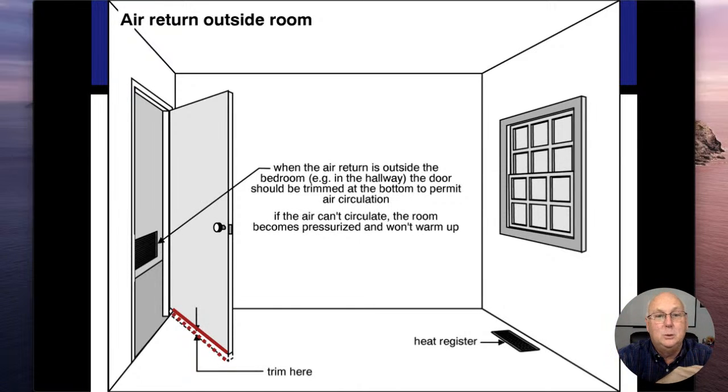One test that I do, and very rarely, but I have found them, where these things are problems: I make sure all the bedroom doors are closed inside, and I'll go into each bedroom door and open it with the furnace running, or the air conditioning running, just as long as there's airflow coming through there. And then I'm going to push that door closed, and I'm going to push it slowly closed.